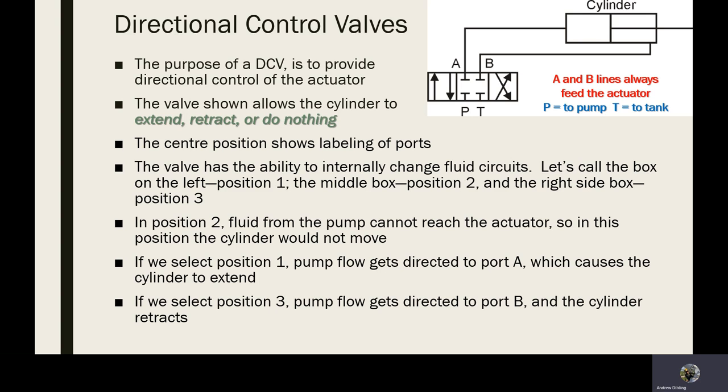Now, a lot of times these will have a middle position where literally it will just send it back to the tank through the filter. Those are used on systems where it's on, off, on, off, on, off all the time, and there may be a high degree of dirt ingress, and you may want your fluid to be cooled. A lot of times it'll just pump up against the pressure relief valve or the pressure control valve and just set the pressure at that. Either way, directional control valves can either be electrically operated or mechanically operated.